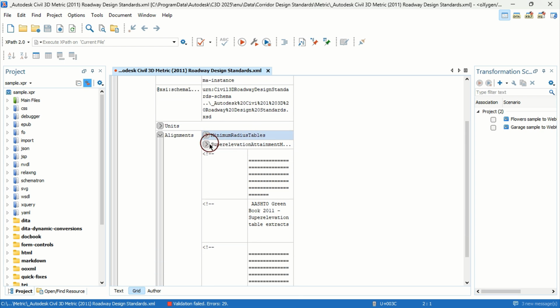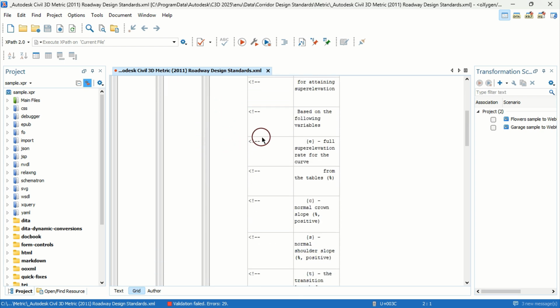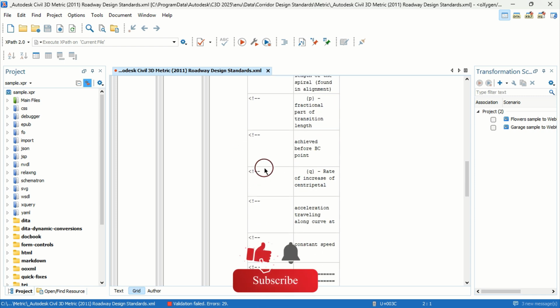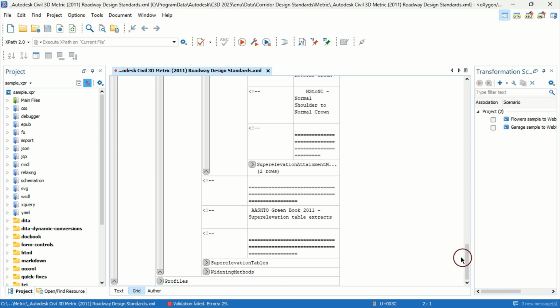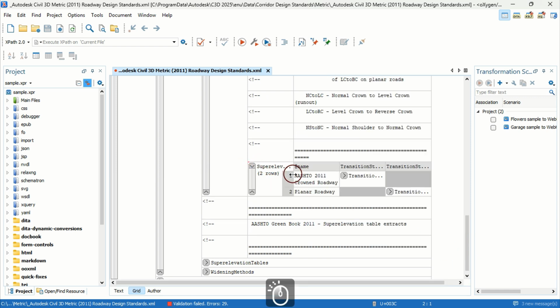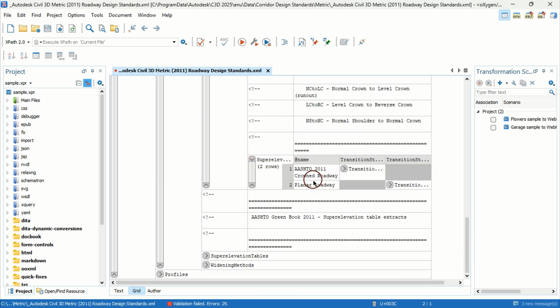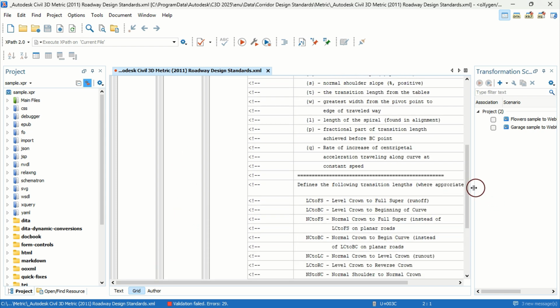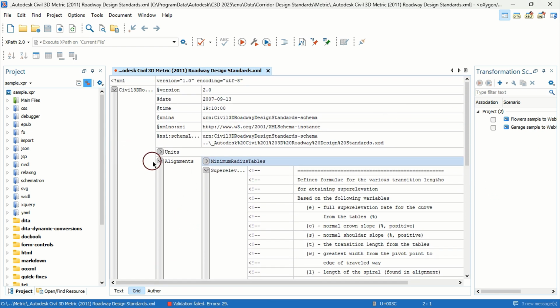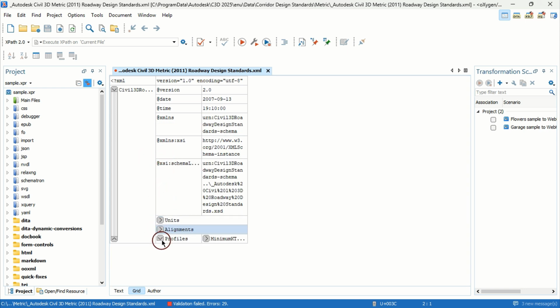You can edit the super elevation attainment method formula from here for alignments with curves. For the formula descriptions, you can expand here to define both the crown and planar roadway transition styles formula as expressed in your country's road manual. Proceed to open the tables that need to be edited, then carefully edit what needs to be edited. You can save time or spare a day to complete editing your criteria file to your standards.